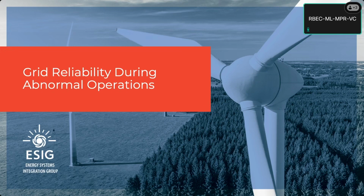If it is part of an IBR interconnection, which it is sometimes, that is defined in IEEE 2800 as, what do they call it? Supplemental device. The device that's in the plant that's not the IBR. So if it's part of a plant, then it gets lumped into the whole interconnection process. But usually the big StatComs are not. And the reason for that is because most IBRs have the StatCom capability built into them. So there's no real need to install voltage control devices with an IBR, because the plants now are essentially voltage source converters, fully rated or close to.